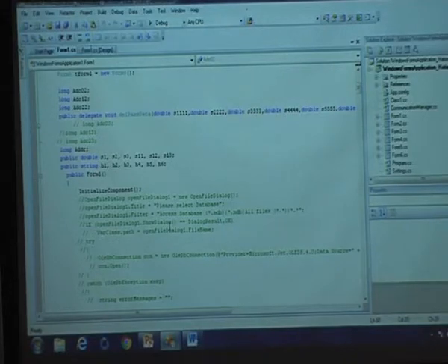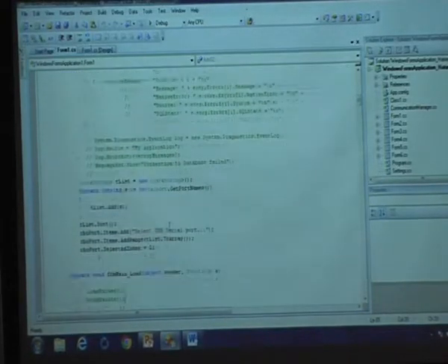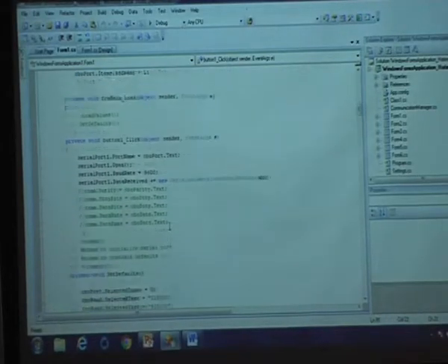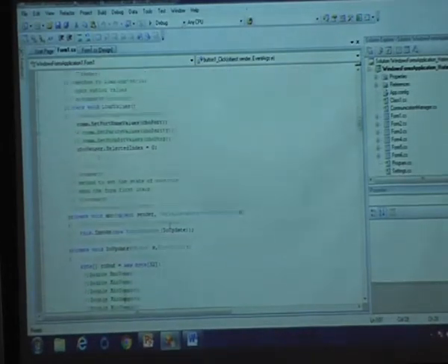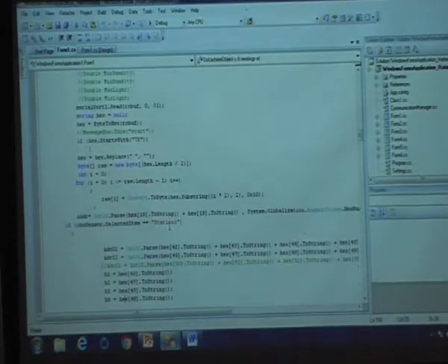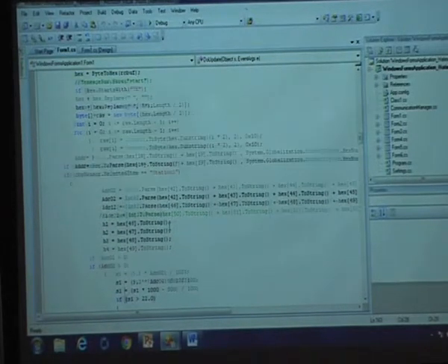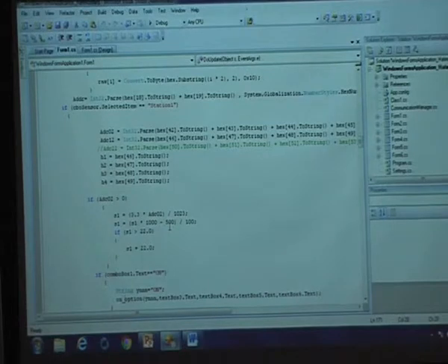So once you take those hexadecimal values of appropriate positions for pin number 20, pin number 19, pin number 18, and so on and so forth. Now ADC02 contains what? ADC02 contains the values of byte number 42, 43, 44 and 45. Those ADC values are being converted and they are being stored in the ADC02 value. Now that ADC02 value is again multiplied by 3.3 and divided by 1023.